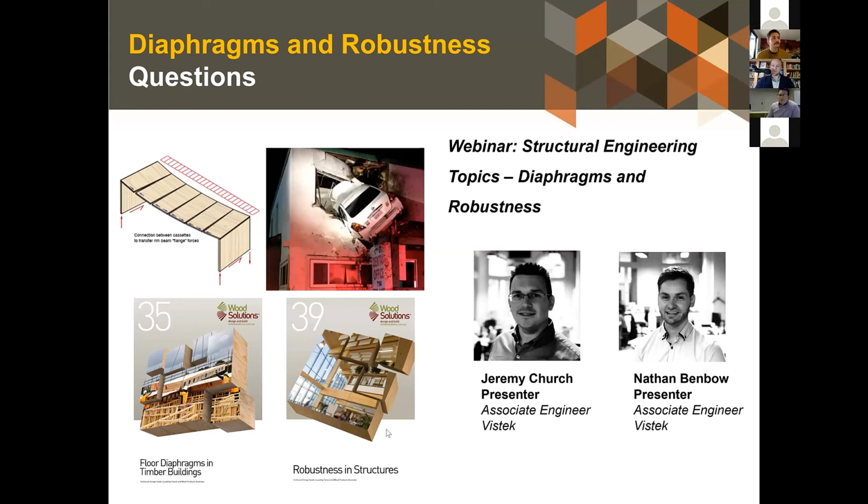Yeah, and just further on that, there are resilient connectors. However, they might be cost prohibitive to implement just to achieve the acoustic performance to satisfy part of the deemed-to-satisfy provisions of the code. Also, you can locate things like your spline connections between discontinuous elements in certain areas.